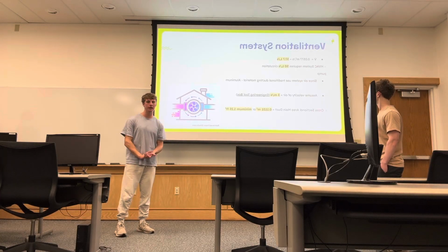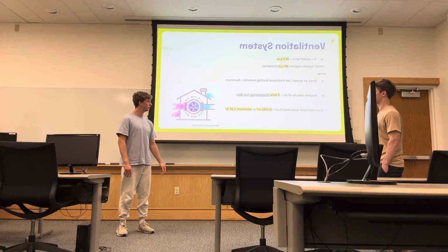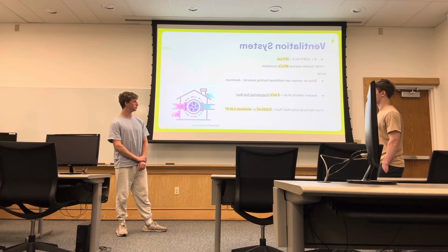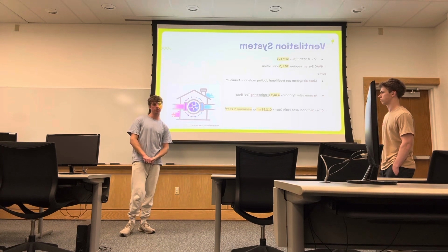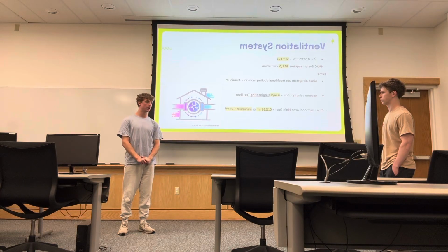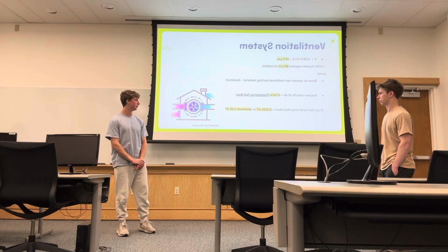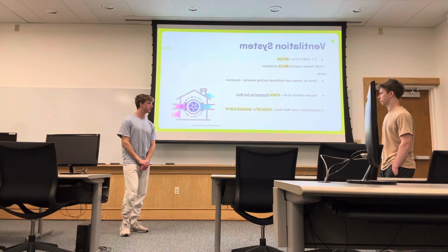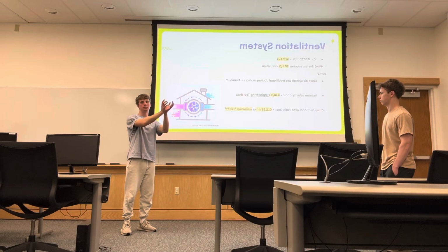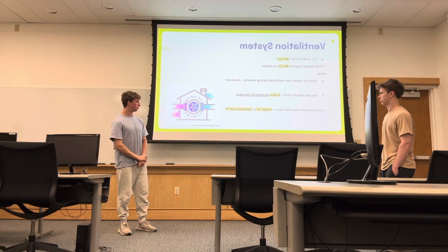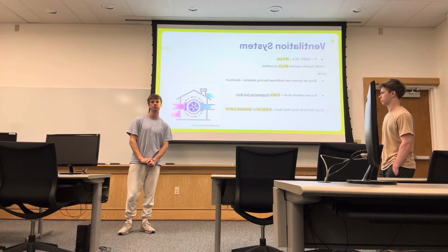Since it's an air-based system, we can use normal traditional ducting materials such as aluminum. According to Engineering Toolbox, for a residential home that has ventilation needs of less than 1,000 meters cubed per hour, the velocity of the air is 3 meters per second. So using that, we can solve for the cross-sectional area of the main duct, which will take the heat from the electric furnace and spread it out throughout the house, to be about 0.11 meters squared, or a minimum ducting cross-sectional area of 1.25 feet squared.